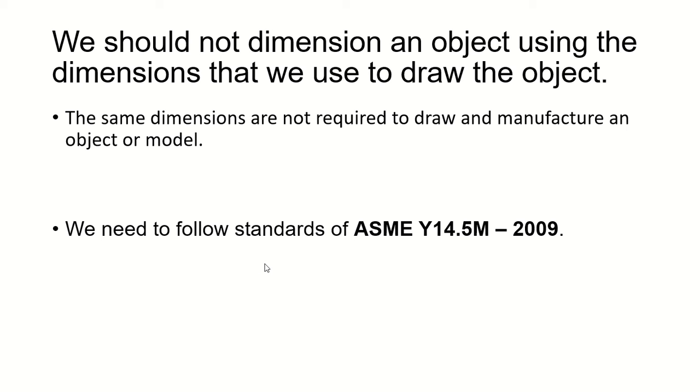For a bigger one, you can size it down, depending on how big the part is. So the actual dimensions are not required to draw, and make sure you follow our standard, strictly ASME Y14.5M 2009. Once again, the same dimension you don't need to draw is needed to manufacture an object.